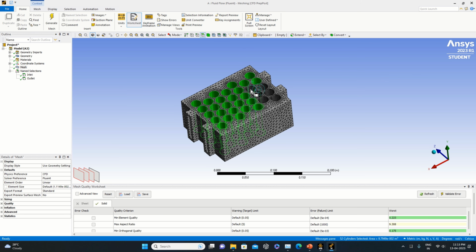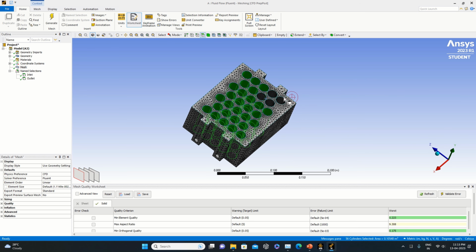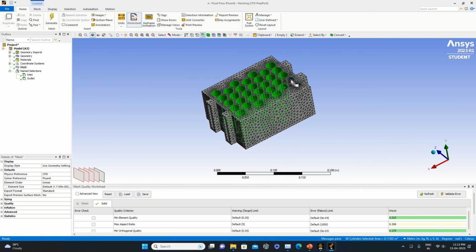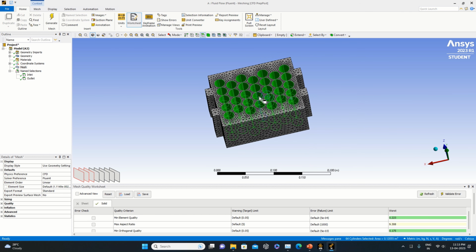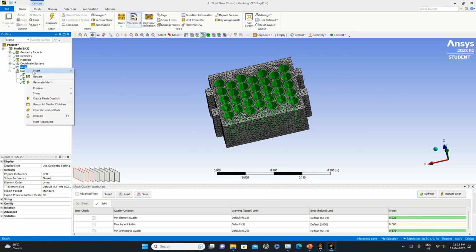We are just selecting all of them so that we can define the object over there, because it has to be specified as a boundary condition. So need to check this one, and this is the last one. So all of them I will specify as a cell wall. So create name selection, I will write this as cell wall. So the lithium ion cell which is there, make it update.